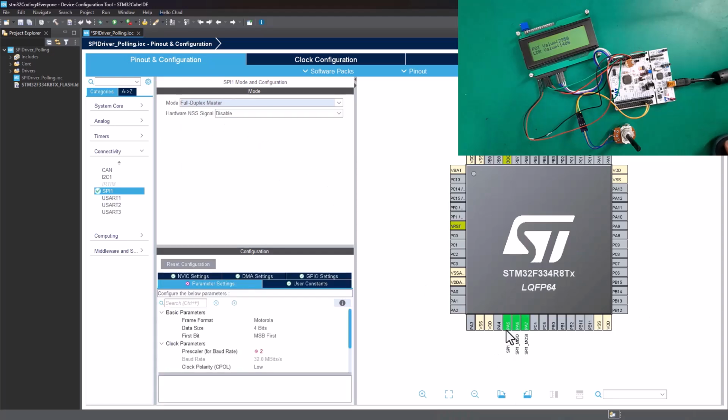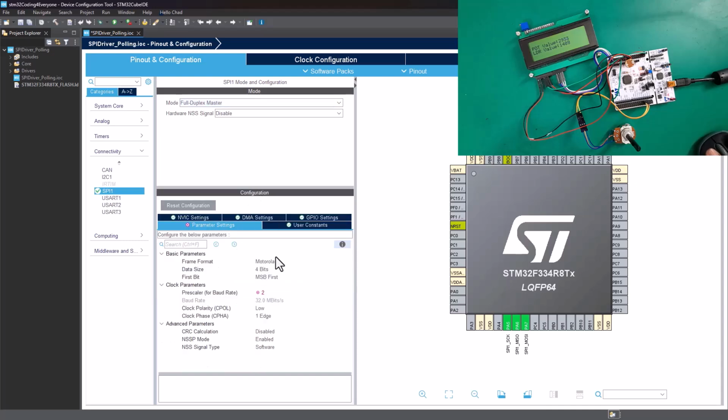And as soon as we select that, our hardware will be configured already with the clock pin selected, the MISO and the MOSI pins selected. But now we still need to configure the setup for our SPI here. Now here, my parameters are already complaining. I've got a red here. When I hover over the 2, it says here, please select a new value other than 2 from the provided list, right? So you might not have this problem here depending on the clock frequency of your mainboard.